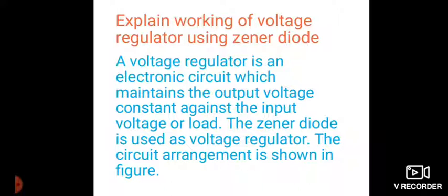So, this property, that the voltage remains constant irrespective of any increase in the input voltage, means that after Zener breakdown the voltage across the diode will not increase, it remains constant. So, what is a regulator? A regulator is a circuit which gives a constant output voltage irrespective of any changes in the input voltage. So, for this application the Zener diode is most suitable in reverse bias.